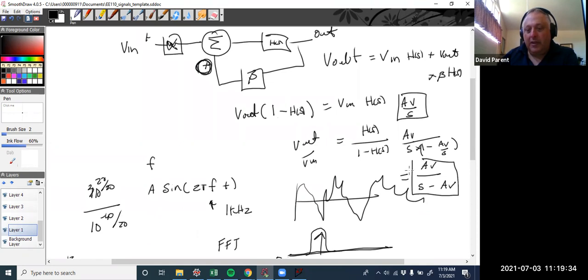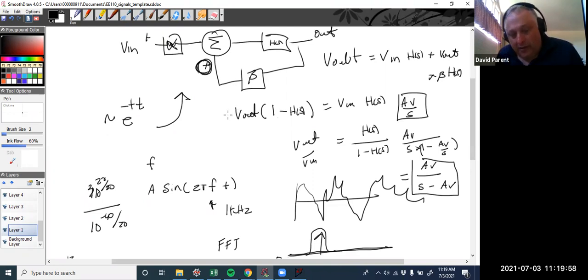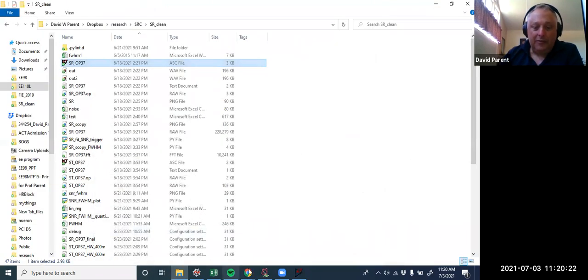well, if you take the inverse Laplace transform of that, it's going to be proportional to e to the plus t, an exponential increase. Now this is a little more complicated, and I have a derivation of it. There are actually two competing exponentials, and it depends on where you start as to which one wins. There'll be an exponential increase up and one down, and it just depends where you start. If you start here, it'll go up. If you start here, it'll go down. All right. And so that's our nonlinear system, this Schmitt trigger.